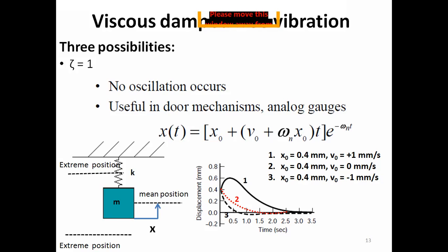And in that damping mechanism, the damping that is kept is critical because we want that the needle moves, but when it becomes stationary, it should not vibrate at that position for longer time. It should get stationary at the reading place so that we take the reading quickly. If the damping in the analog gauges is less than the critical, then the needle would vibrate.